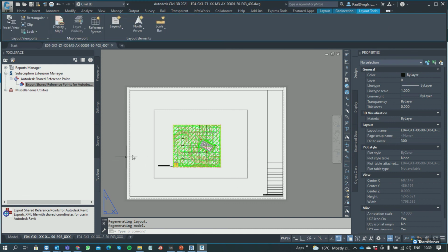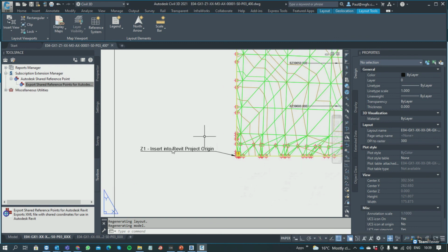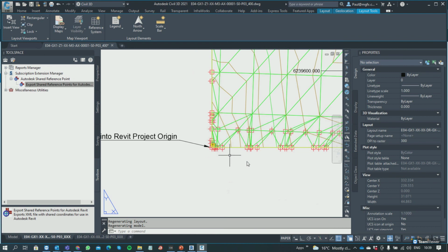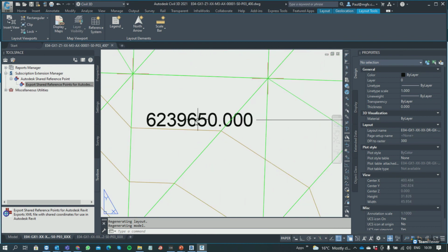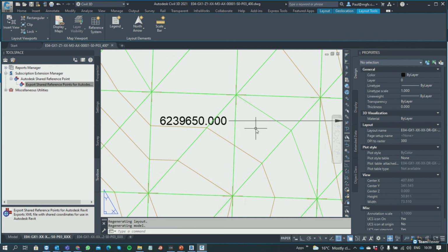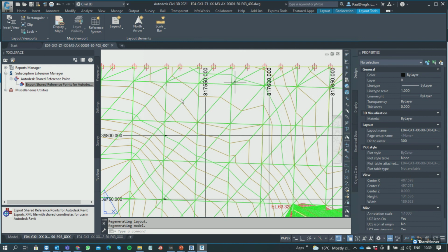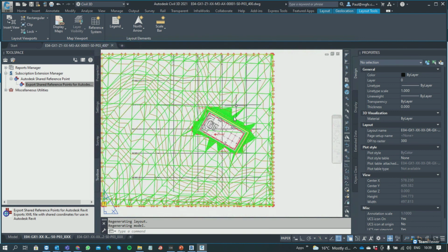Because there are two sites that I want to consider over here, there I've indicated a point to insert onto Revit, as well as a grid line with a label giving me the X and the Y position with reference to the survey beacon. So that's for one of them. And then for the other one,